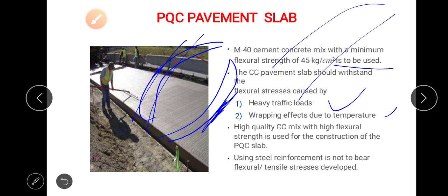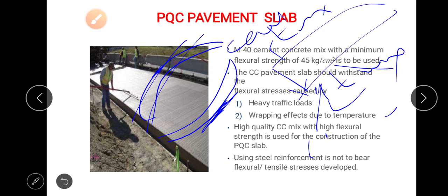Suppose this is the thickness. Here the temperature will be maximum in the midday, whereas the maximum will be at the bottom at midnight because of transformation of temperature from the top layer to the bottommost layer of the cement concrete slab, spreading over the total duration from midday to midnight. Depending upon the temperature gradient, the top layer becomes cool and the bottom layer becomes hot in the midnight. Okay.